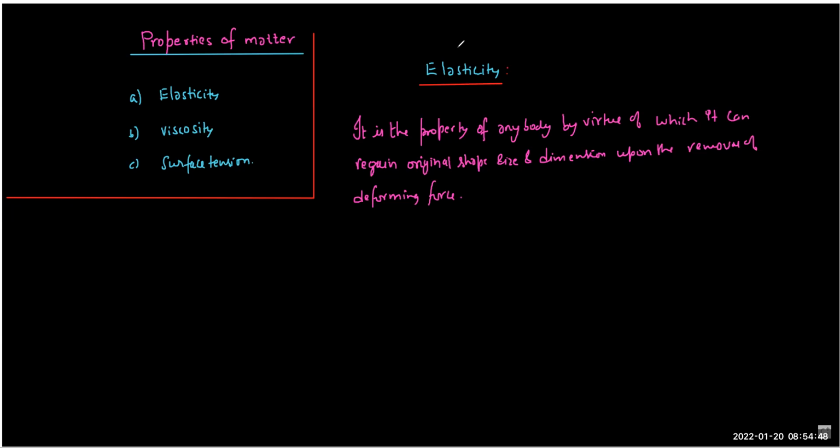Even these rubber bands are very prone to permanent deformation. If you stretch by a long value, it will never recover. It becomes plastic very quickly. But that is not true for the steel bar. It can withstand an even bigger force and still come back to the same dimension.